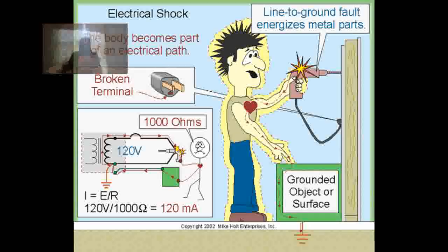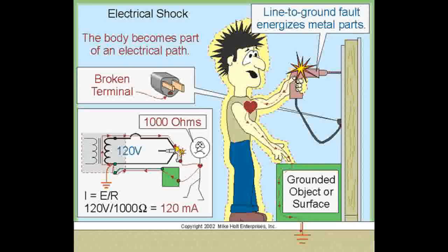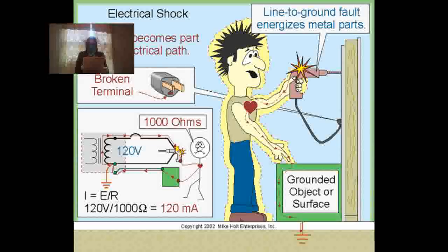Technicians who work on high voltage lines work in insulated bucket trucks or on insulated platforms. Standing on a rubber mat while working on electrical systems is a standard safety and a wise practice. While the technician is standing on an insulated material, there is no direct path to ground in case of an accidental contact with a conductor.